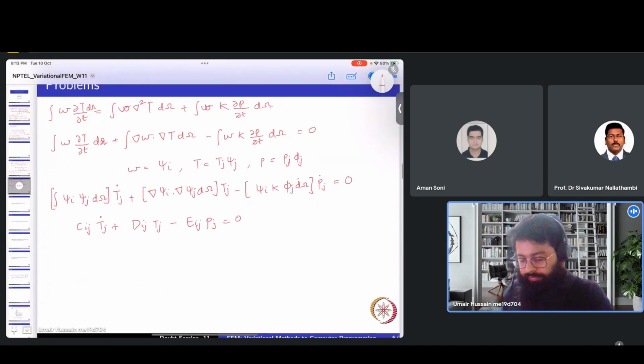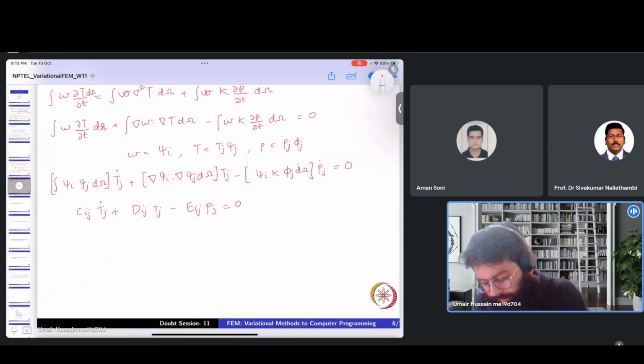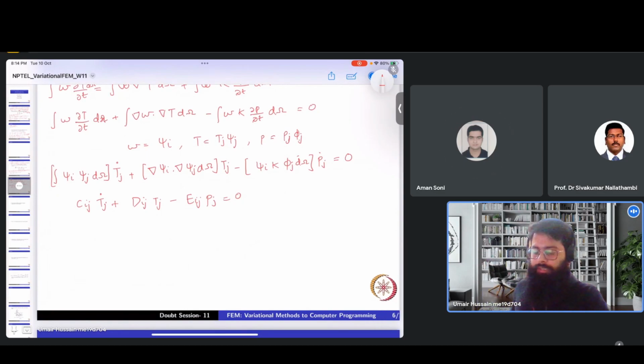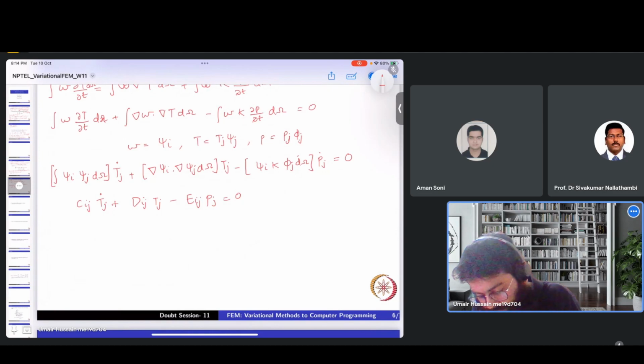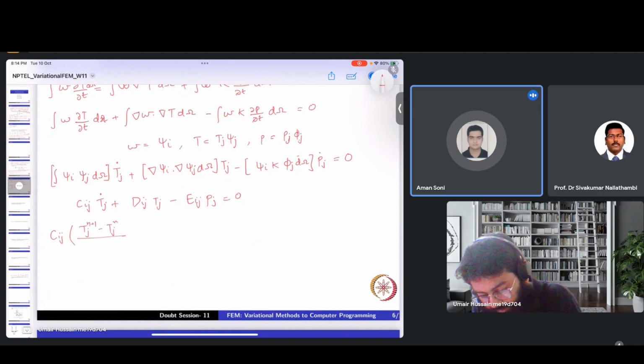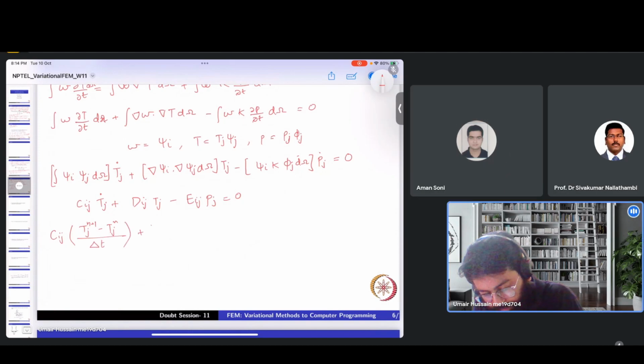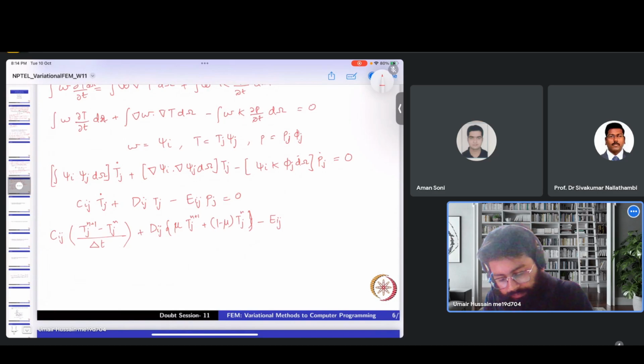So now we discretize this with respect to time. It's clear that Cij is independent of time, Dij is independent of time, and Eij is independent of time, right? So the only thing that would vary is Tj dot, Tj, Pj. So we have to approximate this. Tj dot is Tj^(n+1) minus Tj^n by delta t. Then Dij: here we have mu times Tj^(n+1) plus 1 minus mu times Tj^n. Then we have Eij, mu times Pj^(n+1) plus 1 minus mu times Pj^n.